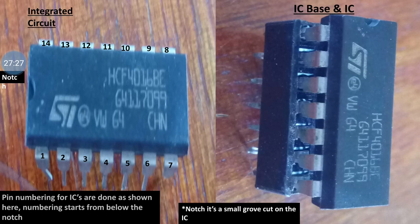So initially we solder in the IC base. Once the IC base is placed, the IC is directly placed into the IC base without soldering. Hence, there is no heating of the IC and you get a protected process of placing the IC.